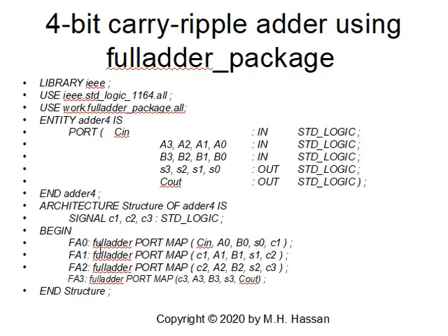So begin. F80 will be the full adder. This is the port map statement. Okay, I have Cn, the carry in, A0, B0 to be added, S0 is the sum, and carry out C1 will be the carry in for the next stage. A1, B1, S1 is the sum bit, and C2 is for the next stage.